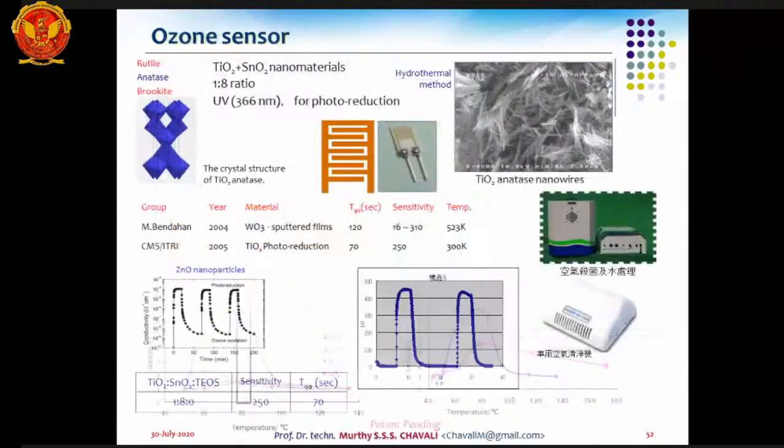And this has been commercialized as a small device, with a size in the order of 10 centimeters, in developed countries. And after that, we got another problem from the industry to develop ozone sensors using SnO2 material. This SnO2, tin oxide, is not going to give a proper sensitivity result. So we had to add this SnO2 to other materials in different proportions.